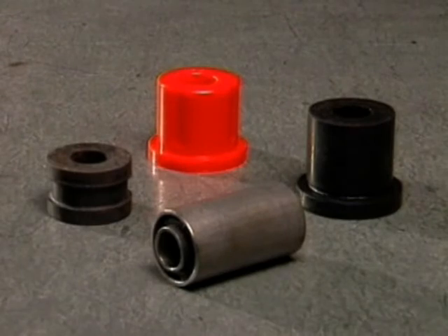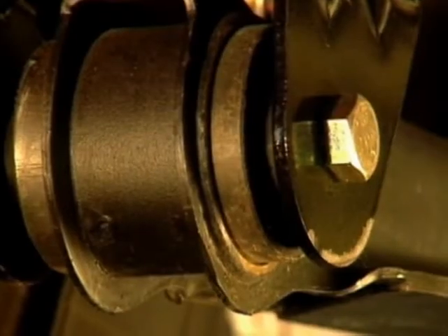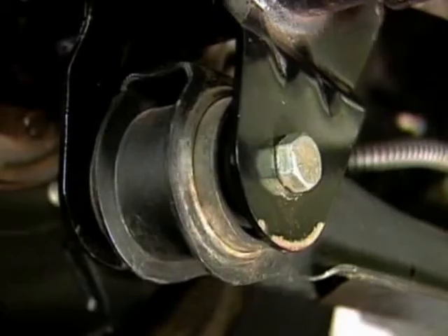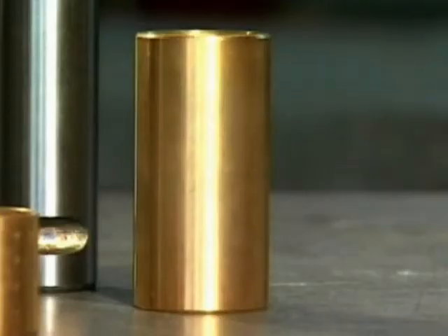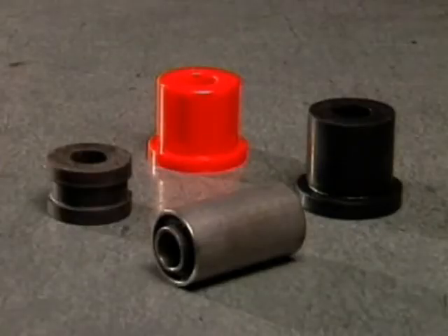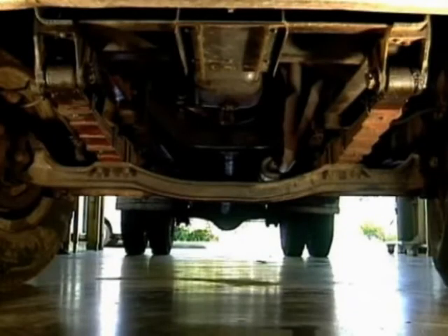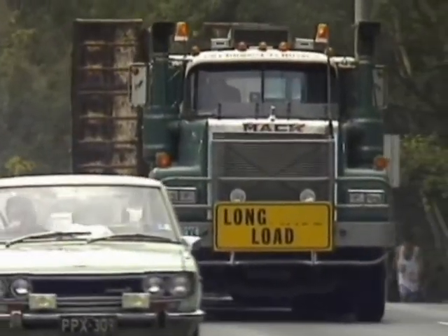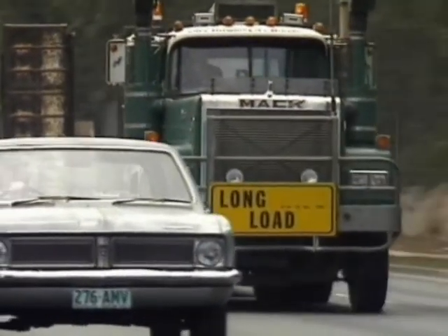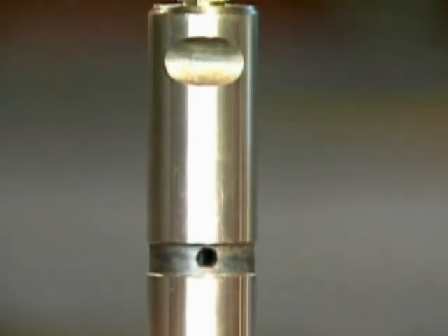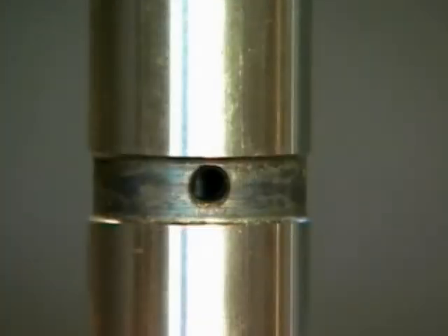This section examines suspension system bushings, in some locations also known as bushes. Bushings act as bearings at suspension fulcrum points to allow for movement of the component while maintaining its alignment. They can be metallic or made of rubber, nylon, or urethane. In commercial vehicles, metallic bushings are commonly used as shackle bushings for leaf springs. Any force applied to the bushing acts through it to the body of the vehicle, which results in a harsher ride. The mounting pin on a metallic bushing is usually drilled to allow for lubrication.